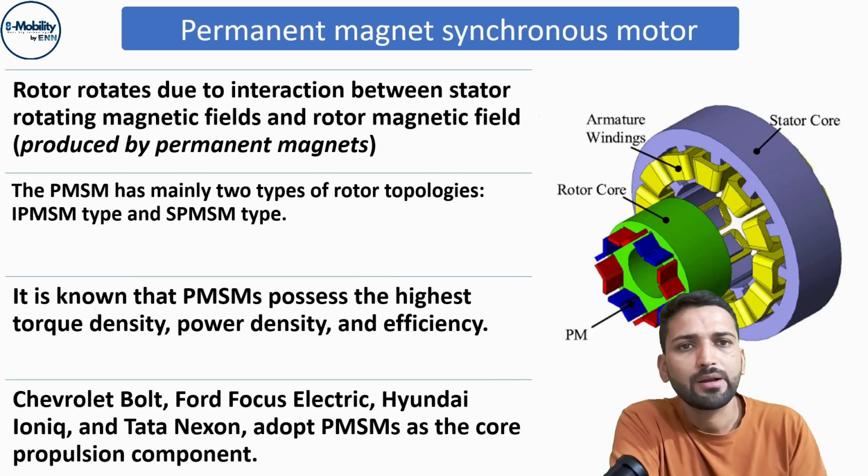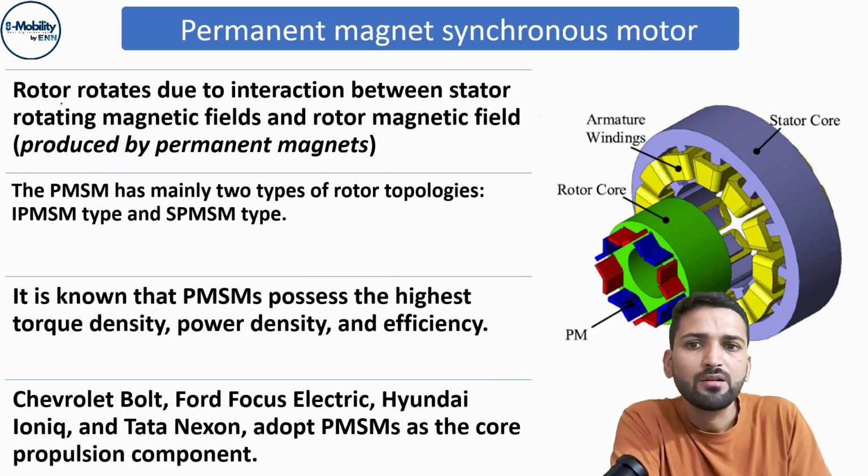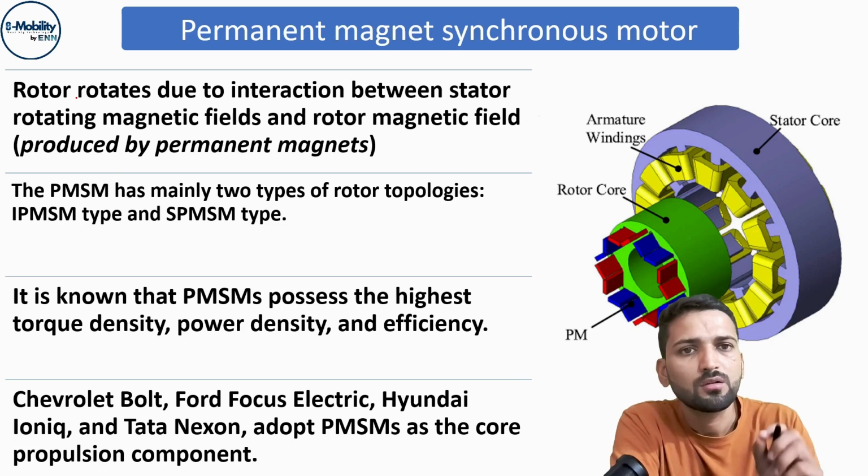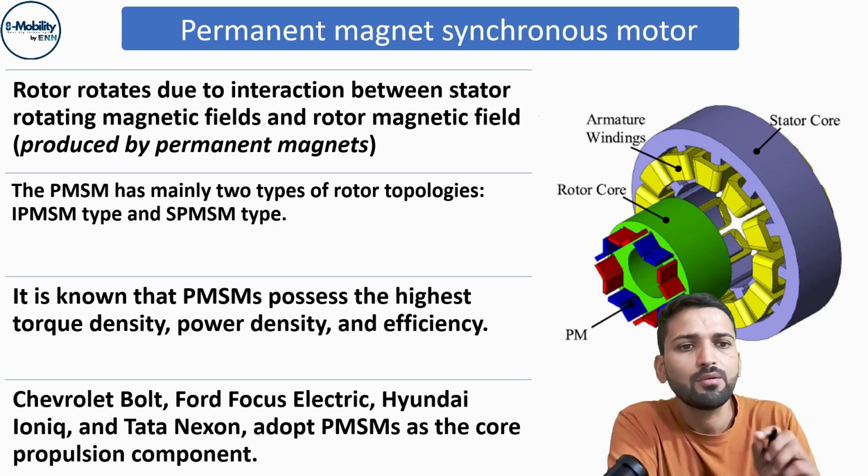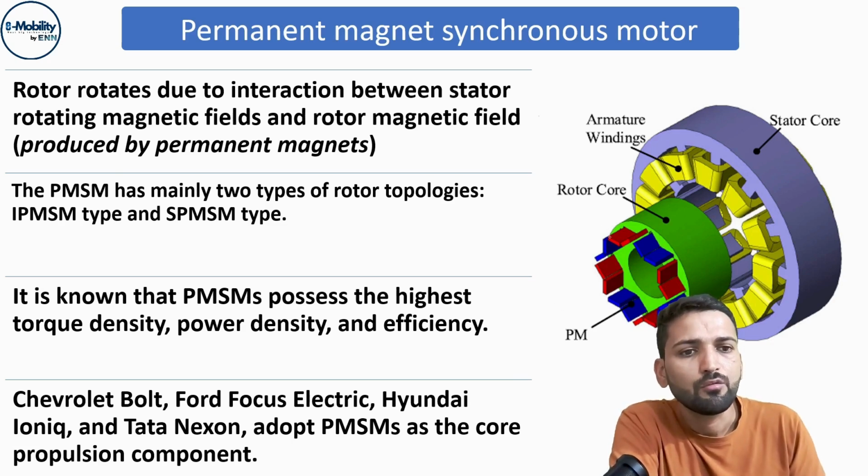Second is the permanent magnet synchronous motor. The permanent magnet synchronous motor also works on a similar principle, except the difference is here we do not need an induced EMF or the induced magnetic field. Here we are putting the magnets.